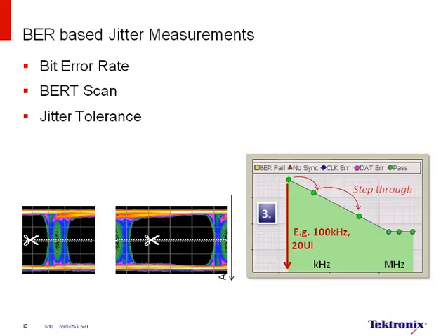Receiver jitter testing has to do with stressing the receiver till you see an error or a bit error ratio or rate that fails a certain spec. Earlier, we spoke about how you can extrapolate to TJ using RJ and DJ. The unique thing about BERTs is that they don't miss any UIs, and they can calculate TJ directly, and from there estimate RJ and DJ. So it's a little different from the way you think of scopes, measuring RJ and DJ, and then extrapolating to TJ.